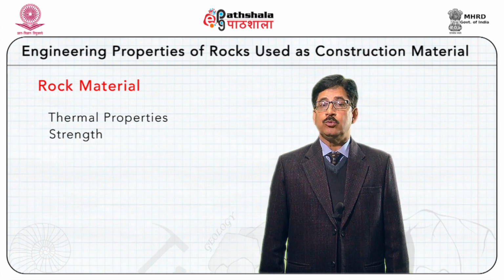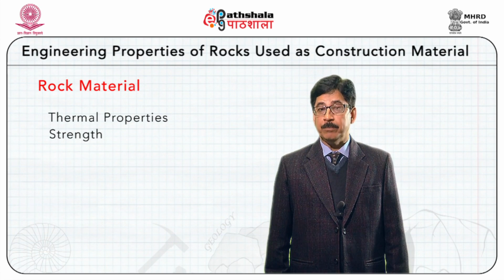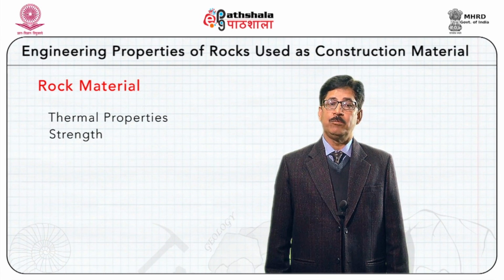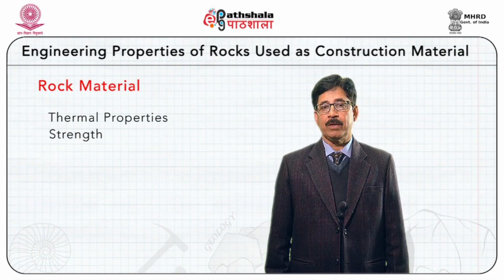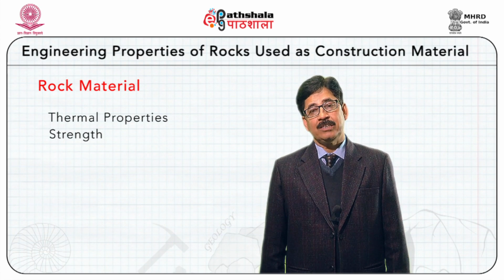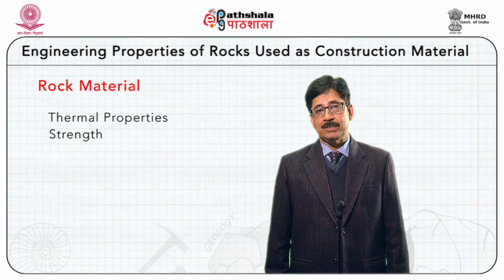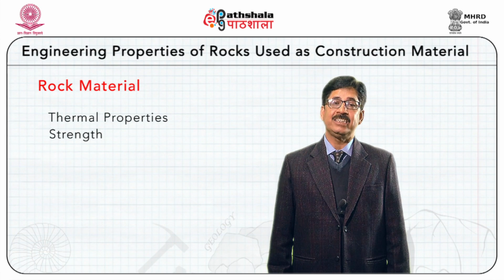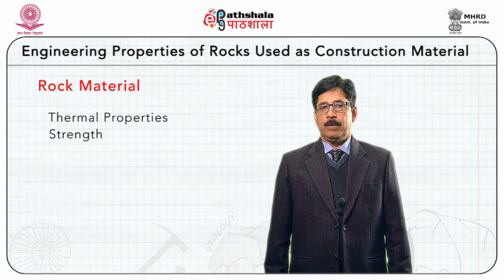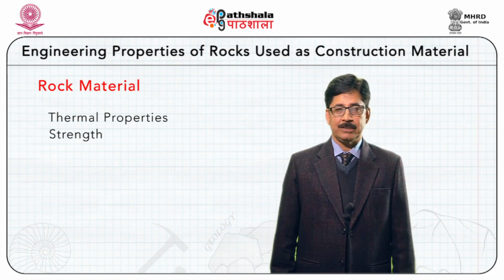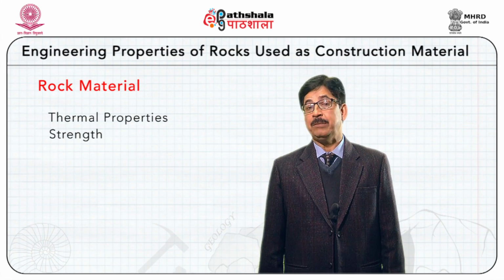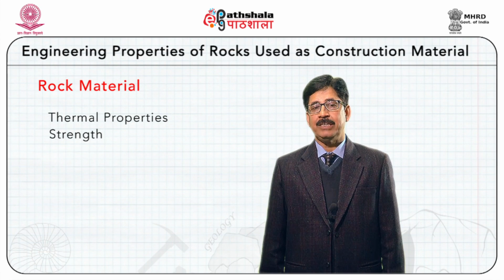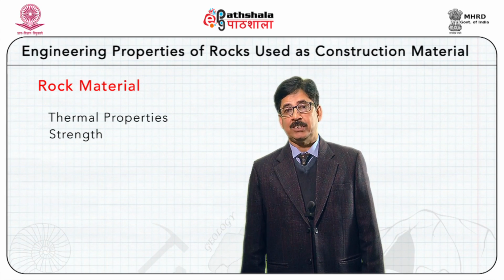Now rocks are sometimes subjected to shear strength, where we are using rock as a beam. So for that, again we have tests for measuring the shear strength of the rocks, and the most important test is the shear box test. Rocks are rarely subjected to tensile strength when we use them in the building. So this test is not very important, but still we normally use an indirect test for measuring the tensile strength of the rock. Rocks are subjected to shearing forces in buildings if they are being used in a column or in a beam. For working out shearing strength, we have the ring or punch shear test, or we can use the shear box to work out the shearing strength of the rocks.